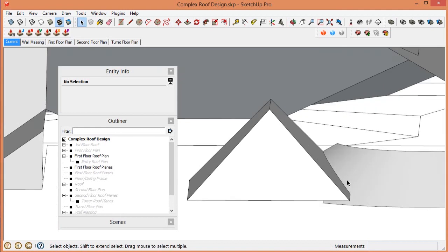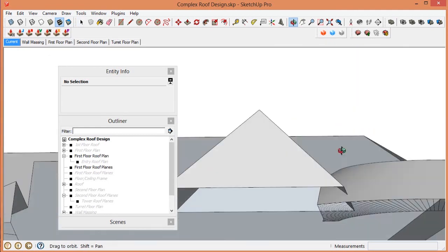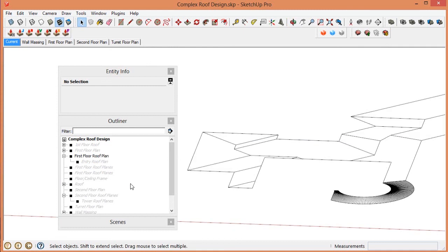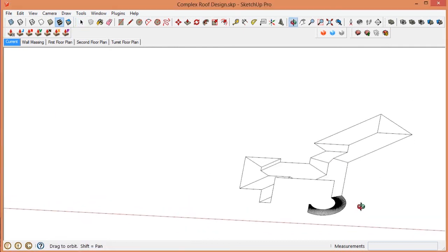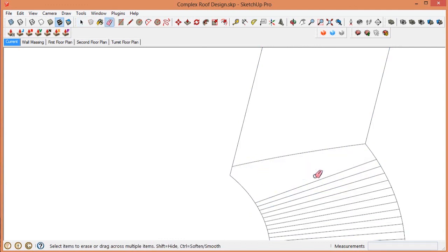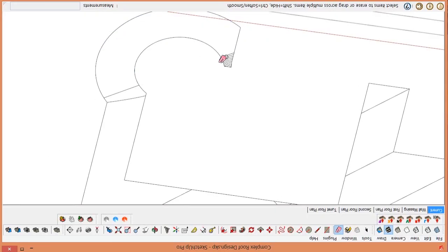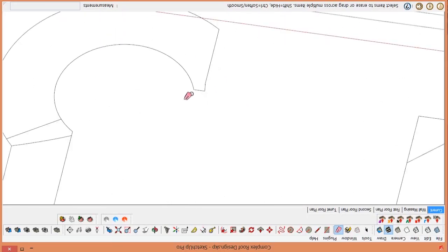And we'll have a little better look at it to see how it fits together, and I believe that is correct. The turret roof will die at the wall, and the entry roof will bear on top of the turret roof. And so now we'll get rid of some of these extra extraneous lines, leaving one that will represent our rafter, which we'll duplicate later.